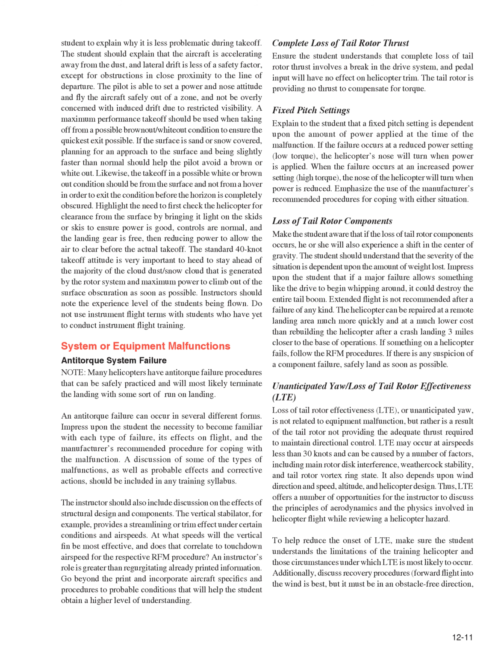Complete loss of tail rotor thrust. Ensure the student understands the complete loss of tail rotor thrust involves a break in the drive system, and pedal input will have no effect on helicopter trim. The tail rotor is providing no thrust to compensate for torque.